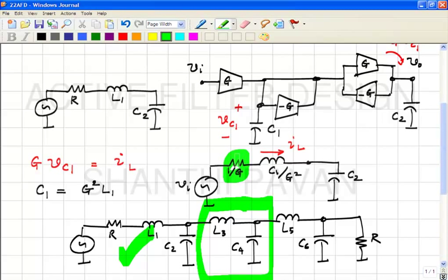here, correct? So in other words, a zero resistance in series with an inductor can be realized by a zero conductance in parallel with a capacitor terminating a gyrator, correct? Please recall that whatever you have at one end of the gyrator, the other end will look like the following.